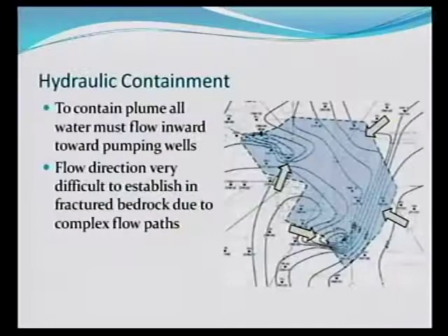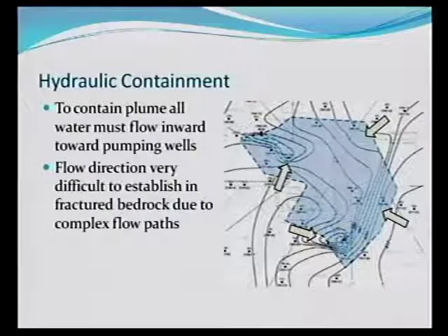So their first need was to contain this hydraulically. Okay, so what the idea was is, here's the landfill. Oh, geez, I can't even see the landfill, it's in there somewhere, but I can't even see it on this picture. But this is the plume from the landfill area. And so the idea was you get a bunch of wells there and you pump it so much that all the water is flowing inward, right? All the water is flowing this way, and then all that water is pumped. Any DNAPL is removed, goes down to an incinerator in Texas.